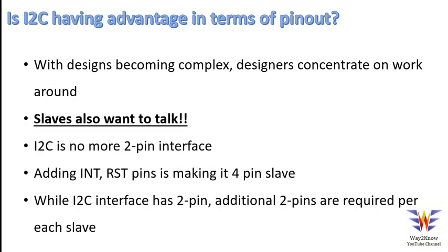Definitely no. The designs are becoming complex these days, and the slaves want to talk rather than only masters controlling them. So the slaves need to have some mechanism to talk to the master. Such mechanisms are the interrupt pins or the reset pins that you see on these slave ICs.